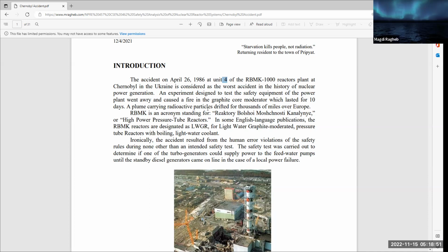All right, in a reactor of the Chernobyl design, the water acts as a poison. So if you get a perturbation and the temperature increases, you'll find that the void fraction increases. The density, again, decreases. But as the density decreases, the moderation increases because the water acts as a poison. It's almost like the control rods being withdrawn. So the power, instead of going down, goes up, and the temperature keeps increasing. And we call this a positive feedback effect. So reactors in the United States cannot be licensed unless they have a negative feedback effect for stability.